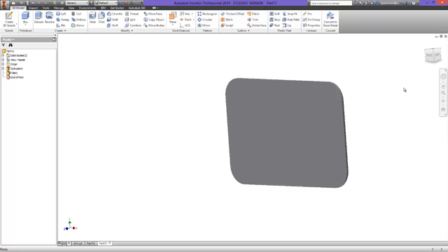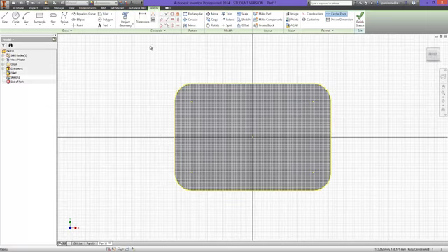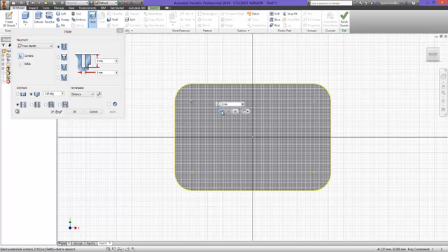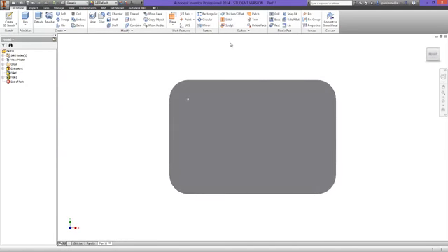So what I'm going to do now is create a rectangular pattern on the front, and then we're going to create a space for the volume control. So the first thing to do would be to right click on the front, create a new sketch, and what I want to do is just insert a hole. I want my hole to be 2 millimeters by 3 millimeters, and select it on that centre point there. Just press OK. So we've created just one hole.